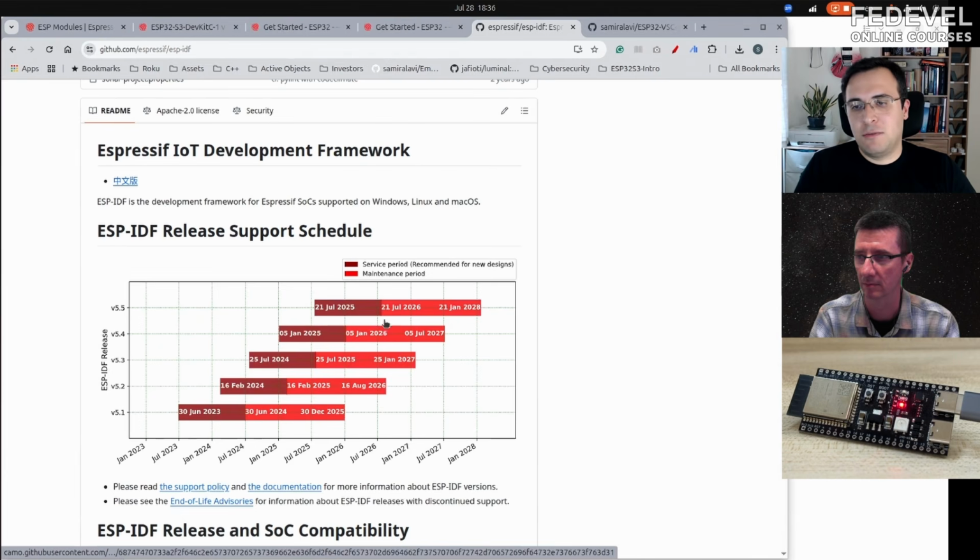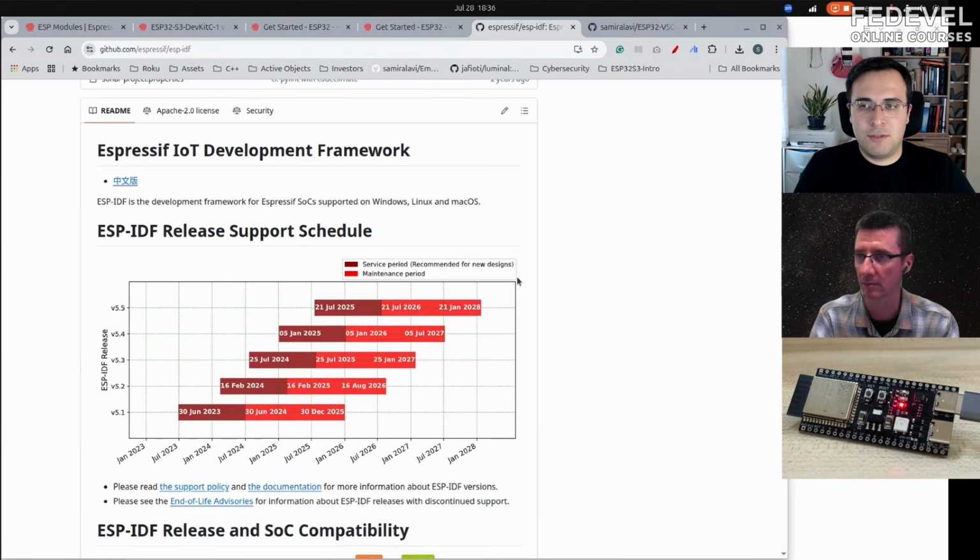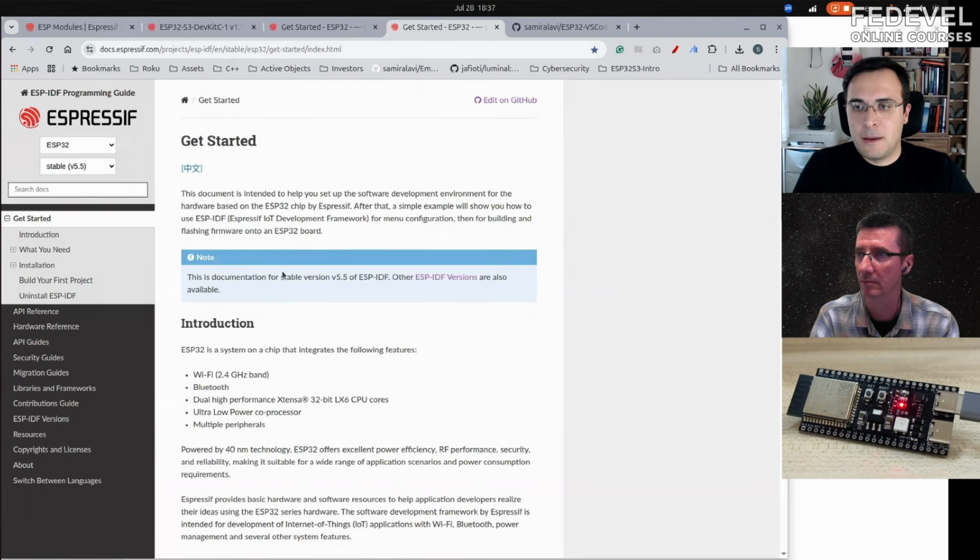If your product, for example, was developed 2 years ago and it supports remote firmware update, you can compile a program with the latest SDK and update the flash memory with it. It's a quite important feature of these Wi-Fi BLE devices. You need to make sure that the device is updatable.